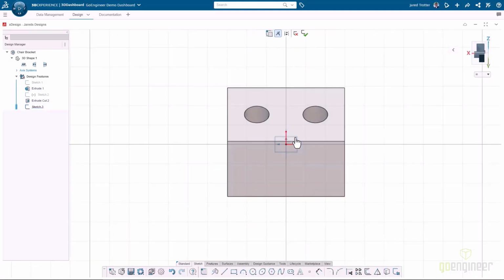So this time, instead of doing this all on the sketch level, we want to apply some geometry just to set the location and take advantage of a more kind of complex feature here. So this is just going to be a line with a couple of points on it to set the location for 2 additional holes. So we got our line, and I just want to grab a couple of points here. We'll put those on there and give them some dimensions. Go ahead and set this up kind of quick here. We don't need anything too fancy here.